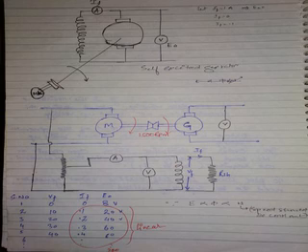This is 1, this is 200. Then again, what happened to point P? Further decreased. This is the point P now, when the field resistance is 200 ohms. Let us say some X ohms, we don't know that. For that particular field resistance, the field resistance line is exactly tangent to OCC. Imagine the field resistance is further increased in such a way that for that resistance value, the field resistance line is exactly tangent to OCC. Let that resistance be RC.